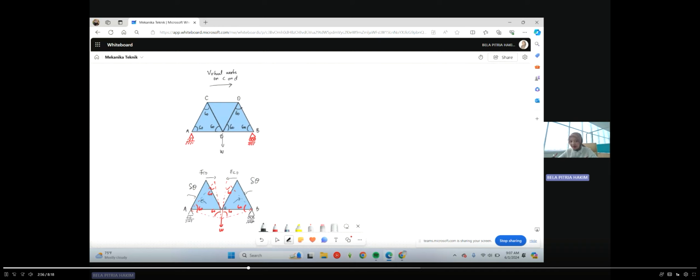Focus on the displacement, something that has changed from the last structure before external forces affected the body. Now we have the change of rotation on both sides, and we try to figure out how to maintain compatibility on E, because it's being pulled at joint E by W.